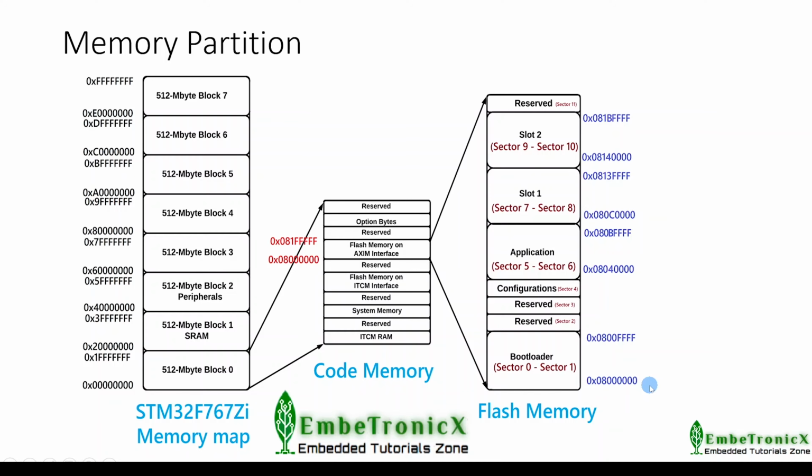In STM32F767GI, 0x00200000 will be accessed by using the ITCM bus, where we have permission only to read and execute and not write. But the address 0x08000000 will be accessed by the AXI bus, where we have read, write and execute permission.